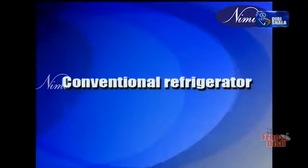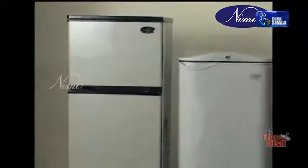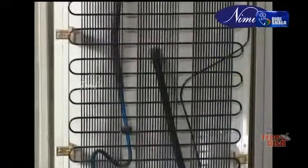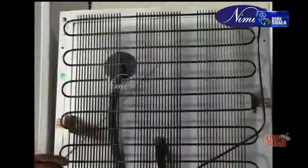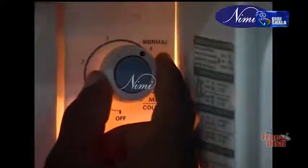Conventional refrigerator. Conventional refrigerators are usually manufactured in different capacities and are normally equipped with hermetically sealed compressor and condenser units. The operation of the refrigeration system works on the vapor compression cycle. The conventional refrigerator consists of components like compressor, condenser, capillary tube expansion device, evaporator, filter, and temperature control.